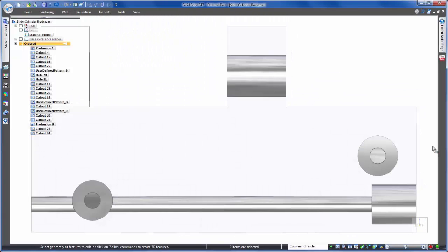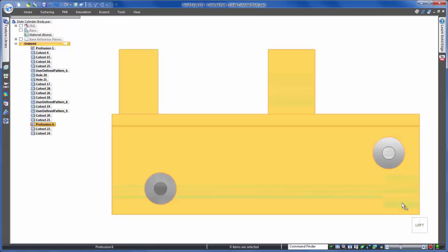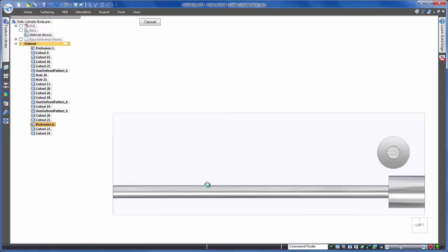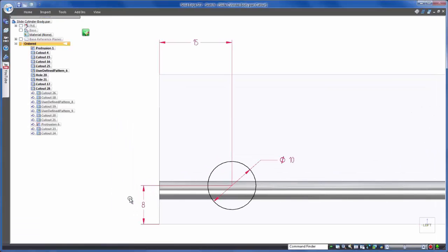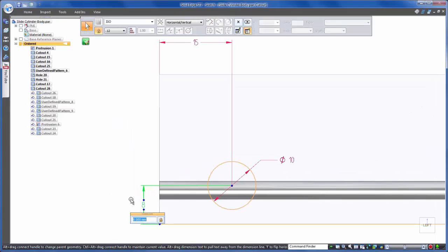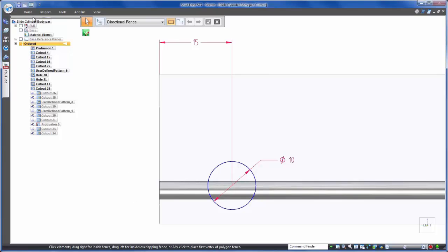Again, the setup of the original design intent means that the model hasn't changed as expected. We anticipated the back hole to stay in line with the front hole edited earlier. As we look at the profile, we can see that the hole has simply been dimensioned to the bottom of the part to match the dimension on the front side.